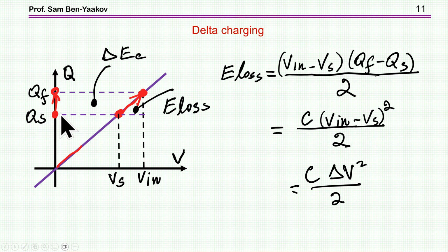So let's look at another case in which I'm tapping off. That is, the capacitor is charged to Vs and I'm recharging it to Vin, and this is going to completion, okay? So this is like in the case of a bootstrap, for example, for a power supply for a high side gate driver will be the case that we are tapping off the energy from time to time, okay?